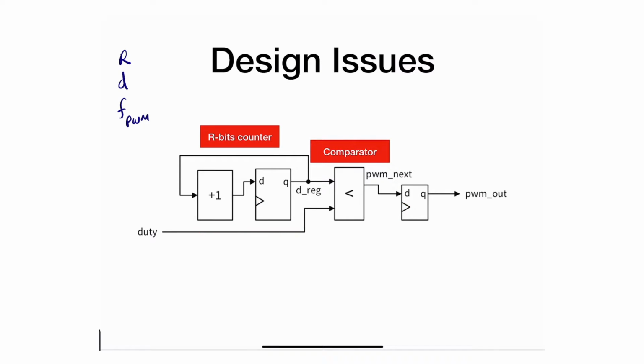In order to change the time at which this counter changes its count, we should add a Prescaler Counter, which is a different counter that does exactly the same thing, but instead outputs a tick at a very specific period of time, and that tick is connected in here and enables the second one.